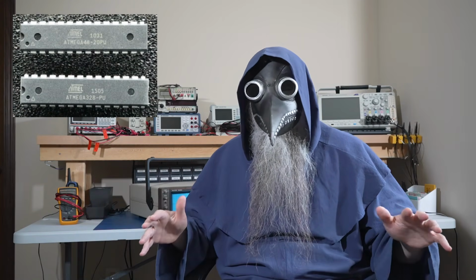Now, if you're not familiar with the ATmega48, you may know of the ATmega328, which is its bigger brother, if you will. The ATmega328 was used on the Arduino Uno and has much more memory than the Mega 48. The Mega 48 only has 4K of flash, while the Mega 328 has 32K. But even with only 4K, I was able to make a very capable video game circuit. It wasn't spectacular by any means. It was probably similar to the capabilities of the old Atari 2600 system. So, if I was able to do something like that with only 4K, then imagine what you could do with 32K.